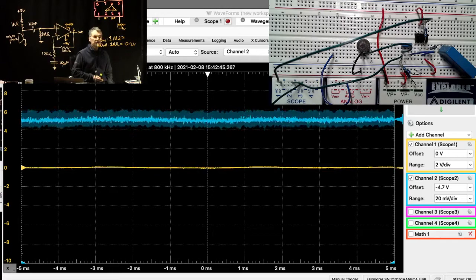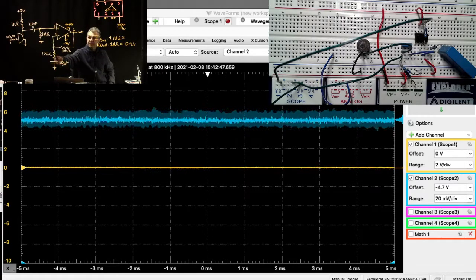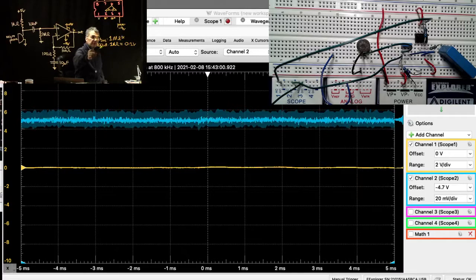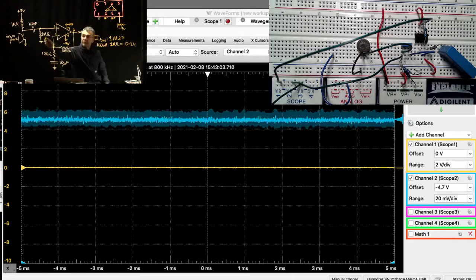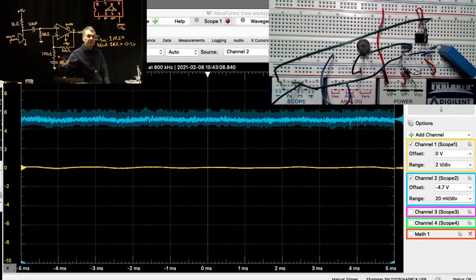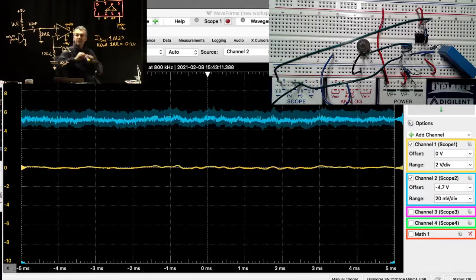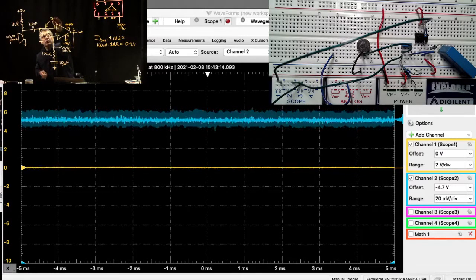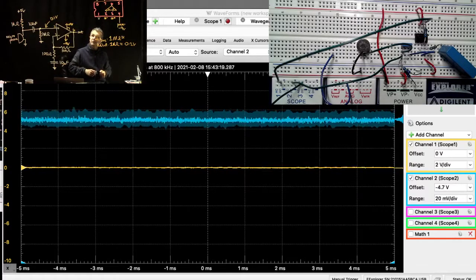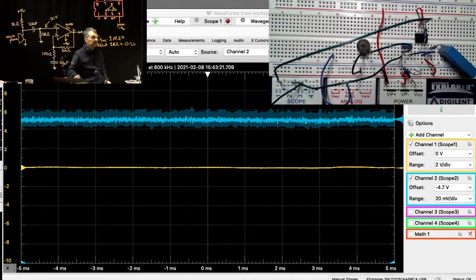So then what you're going to see is that the gain becomes 101 everywhere. Right now the DC gain is only 1. So if we do that, the DC gain will become 101. And then remember, I bias is about 80 nanoamps. We'll just round it off to 100. So 100 nanoamps times 1 mega ohm will give us 0.1 volts. So effectively we should get about 0.1 volt here, and you multiply that by 101 and it gives you about 10 volts. So that should be big enough to saturate the output.